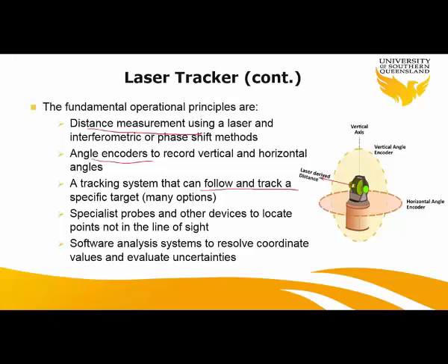It's pretty much like a tracking system we have in the total station. It can also use the probe to get access to the points which are not in the line of sight. So if you have a big machinery that you are not able to access or put the target and measure directly, you might use the probe. I will show you the example of that, and I put the video on the study desk that you can go and watch it.